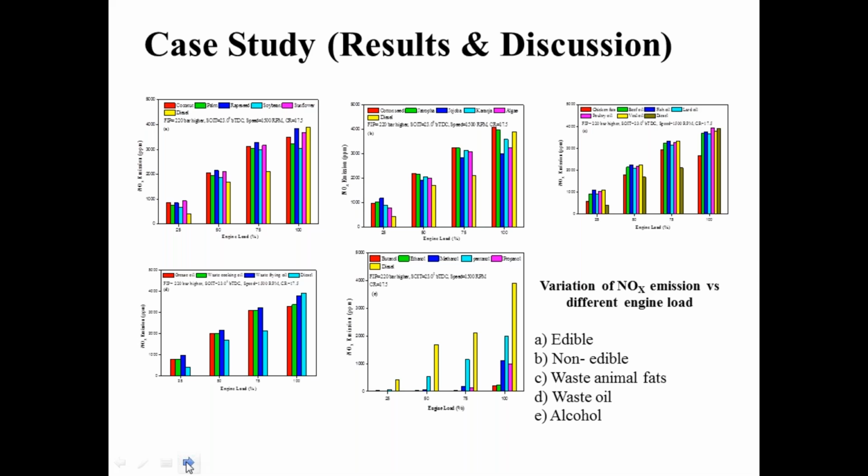There are 5 diagrams. NOx emission, the nitric oxide and NO2 emission, is generated during the combustion process due to the reaction of oxygen and nitrogen at high temperatures. The main reason for NOx emission produced in the combustion process is the oxygen present in the free air. Regular fossil fuel has a trace amount of nitrogen molecules in its structure, but the nitrogen content within the fuel has an effect on nitric oxide emissions.